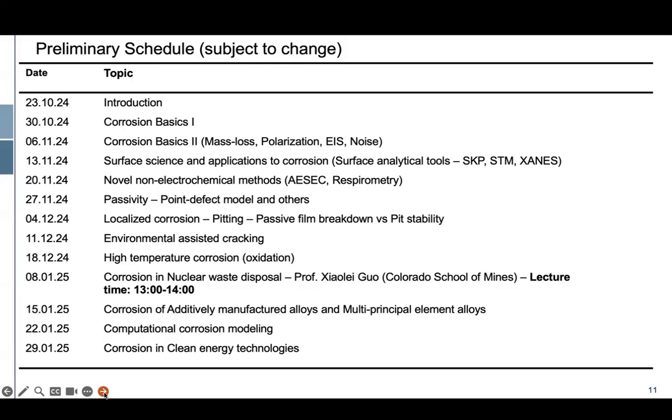And then I will also introduce you to different approaches to tackle corrosion problems, such as changing your alloy composition, designing new alloys, or usage of coatings, inhibitors, and cathodic protection. And finally, we will talk about different corrosion measurements, starting from simple mass loss. You immerse the material and take it out and measure how much mass loss has happened, or mass gain that might happen. And then we have electrochemical methods, including polarization, electrochemical impedance spectroscopy, and electrochemical noise, etc. So this will be the goal of the first chapter.